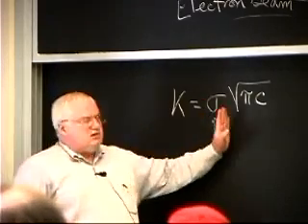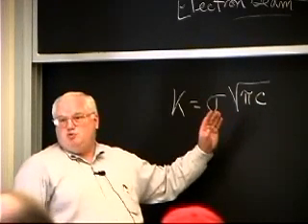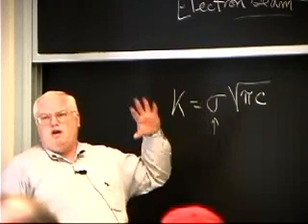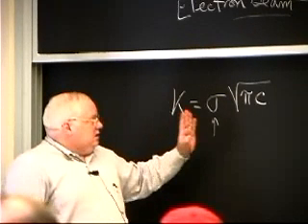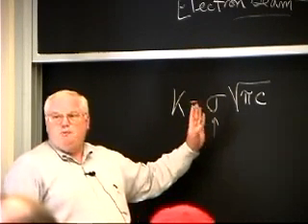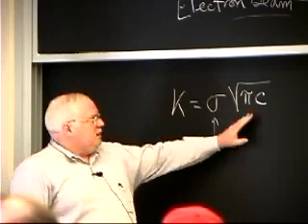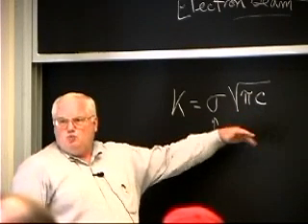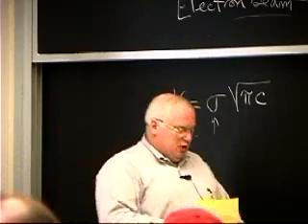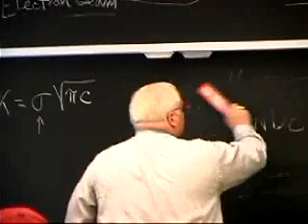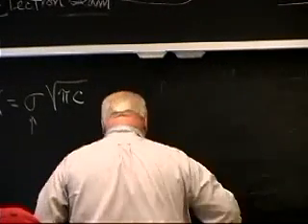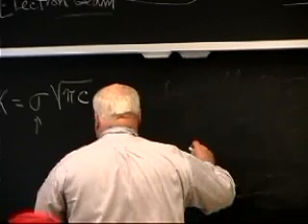And the stress intensity is a part of 2 things. The stress, which we calculate very well now. I mean, we've got finite element programs that will calculate this pretty accurately, to within a couple of percent. However, the flaw size: what's the flaw size, and population and distribution? And us consultants can still make lots of money arguing with people over this.